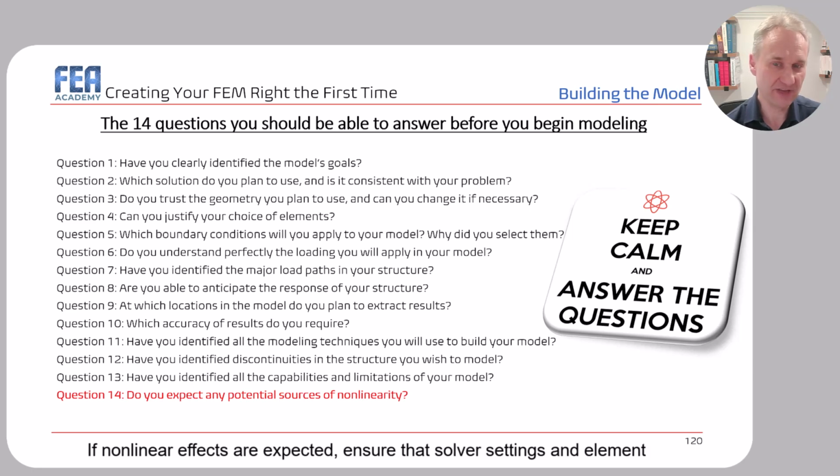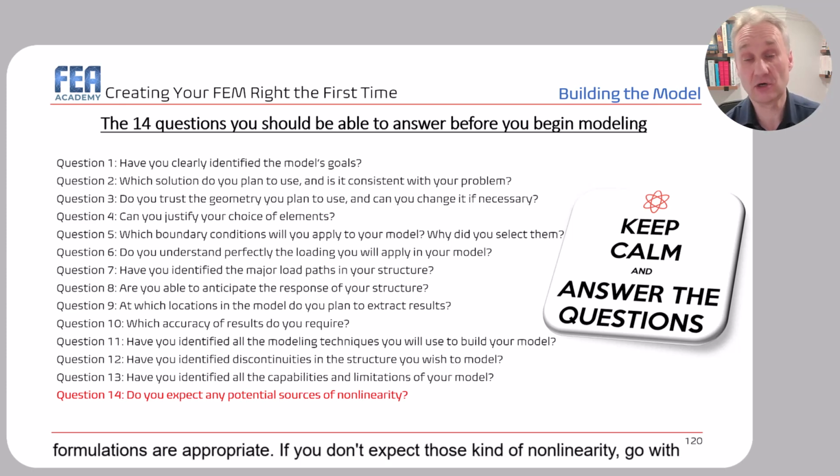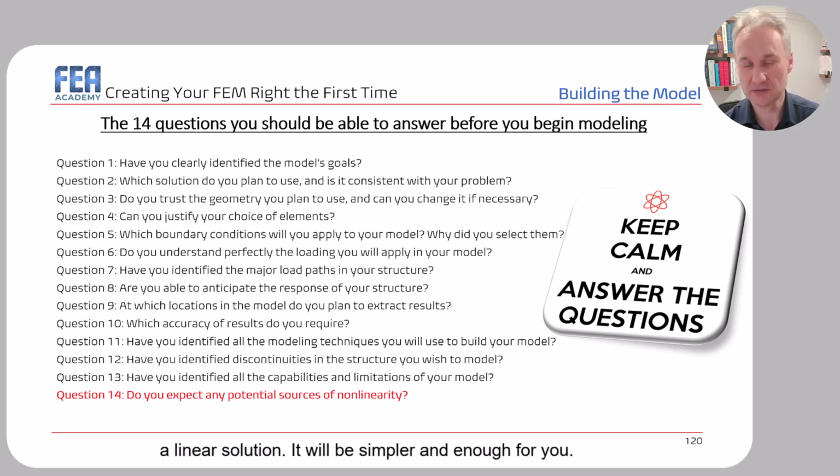If nonlinear effects are expected, ensure that solver settings and element formulations are appropriate. And if you don't expect those kinds of nonlinearity, go with a linear solution. It will be simpler and enough for you.